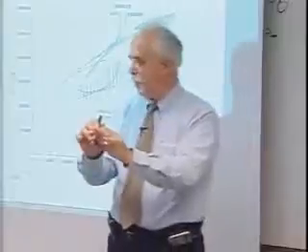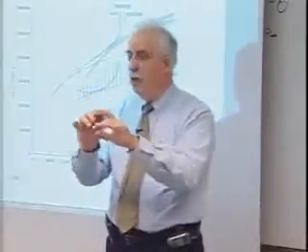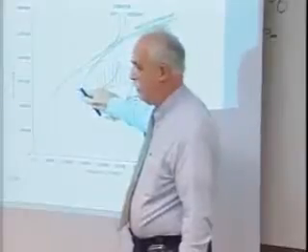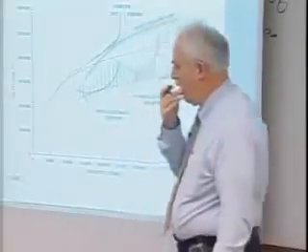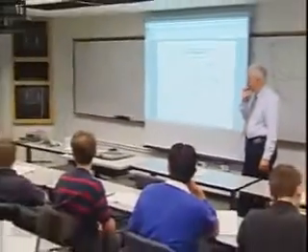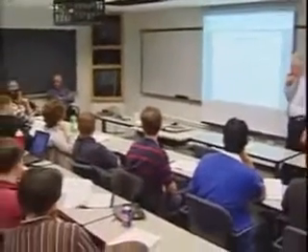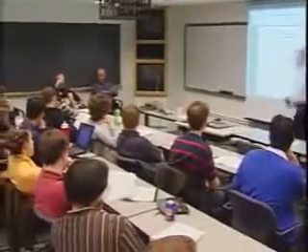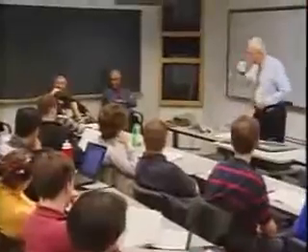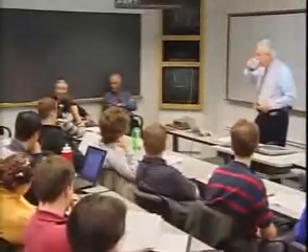So first thing is capture, dissipate that energy. Then we worry about getting down to a landing point. They term that corridor. The Apollo vehicle had about a 27-mile corridor at 400,000 feet. If you were too shallow, you would skip out. If you were too steep in that corridor, you would go in too deep and exceed the G load.